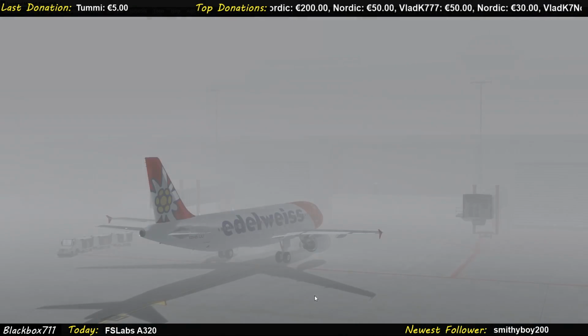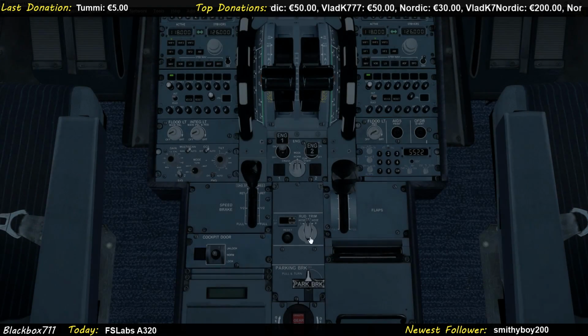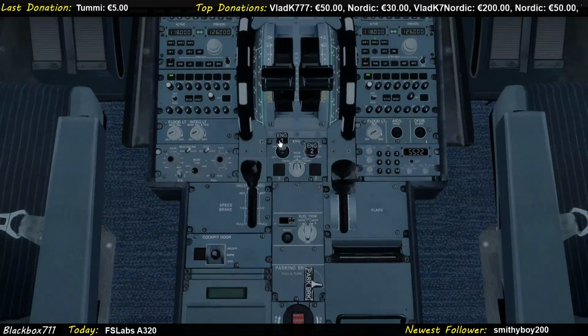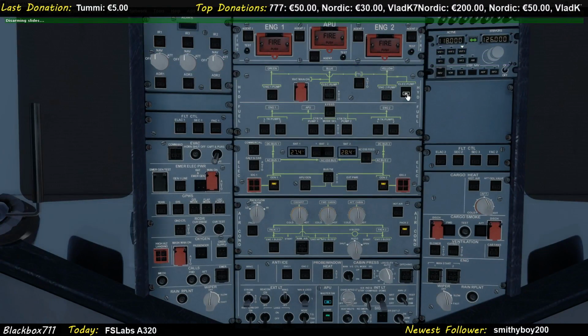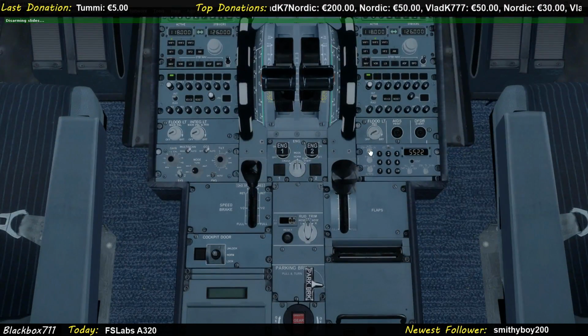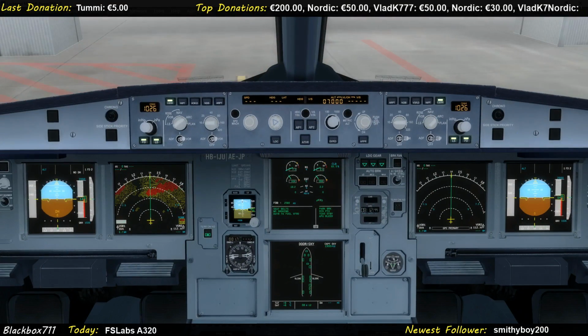Ooh. Wow. All right, we'll stop here. Setting the parking brake. So the APU is running. We can switch off both engines now. And remember to switch off the yellow hydraulic pump because it'll continue to screech like hell and passengers are going to really be upset. So I'm going to switch off the beacon as well. And transponder is going off. Protective windshield, radar is off. And then we'll read the parking checklist.